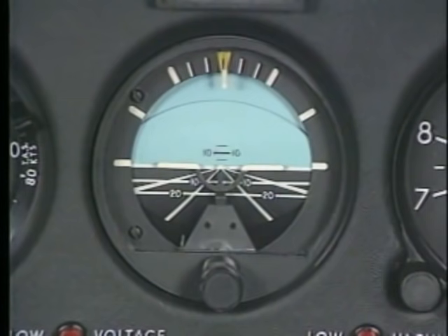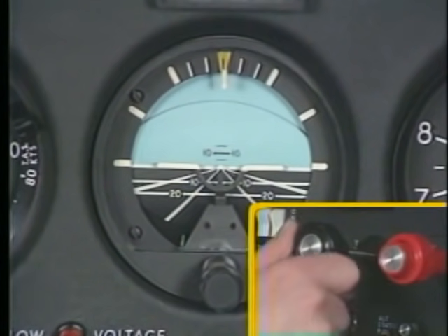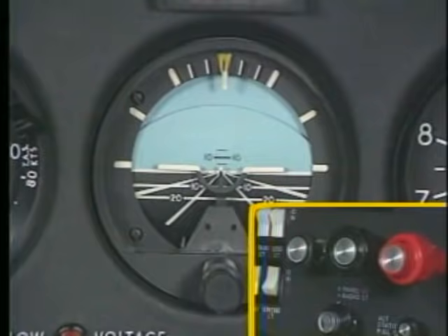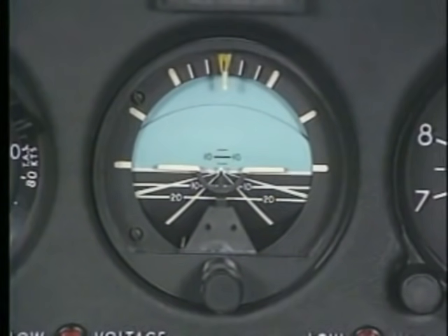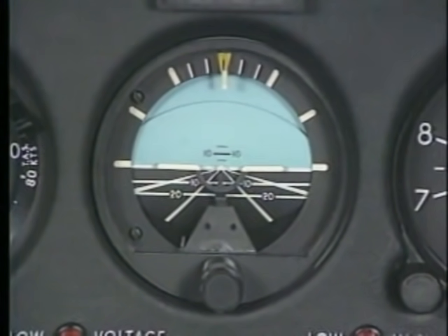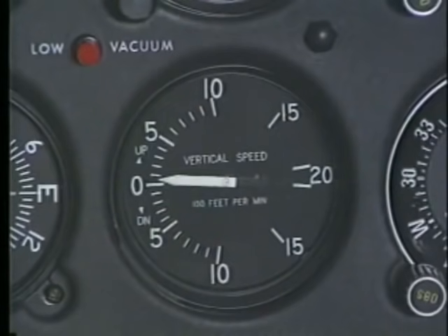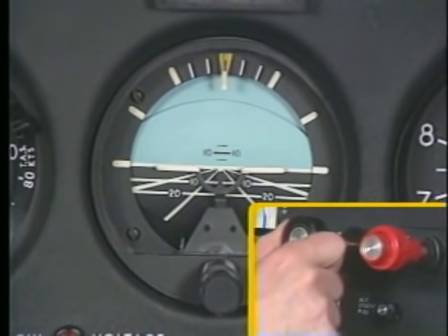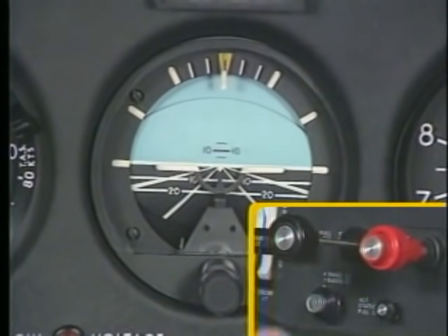However, because of precession, the attitude indicator could give you erroneous indications. For example, if you accelerate rapidly, the instrument may indicate a slight climb. If your reaction is to lower the nose to return the miniature airplane back to level, your actual pitch attitude will be lower than that shown on the instrument. This will place your airplane in a descent unless you take corrective action. The opposite occurs when you decelerate rapidly. Here, the initial indication is that of a slight descent.